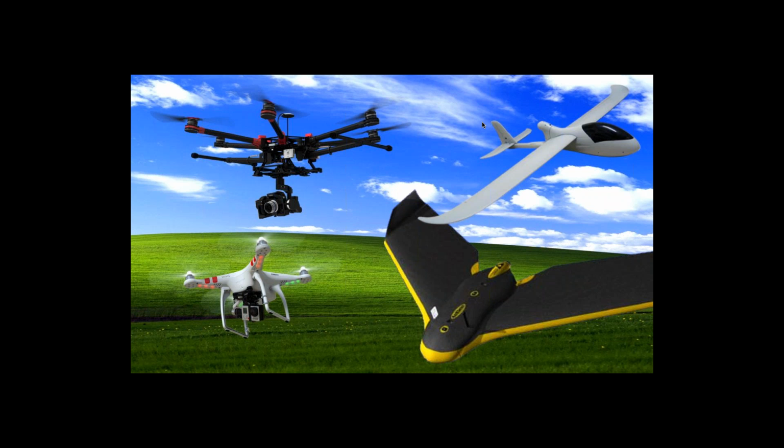The multi-copters are typically launched in a flat area. They can be autonomously programmed. The wings are launched by hand typically, so you need an open area to launch and to land the wings. So there are some strengths and benefits of each of those platforms. And at the end of the day, any of those platforms can collect the data. So it just depends on what's available and what the mission is. You might be able to fly longer with the wings, for instance, but you can get up closer to a bridge with a multi-copter.